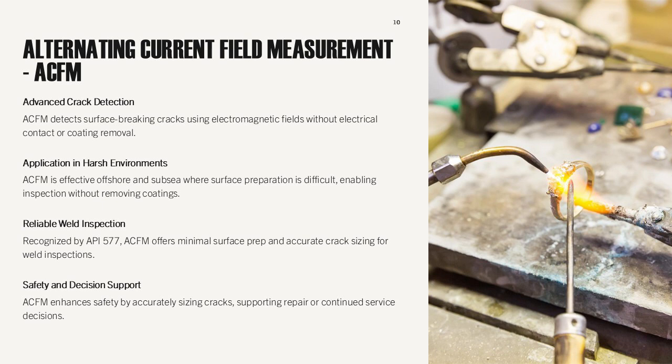ACFM is particularly useful in offshore and subsea environments where coatings cannot be removed easily. API 577 recognizes ACFM as a reliable method for weld inspection, offering advantages such as minimal surface preparation and the ability to operate in harsh conditions.